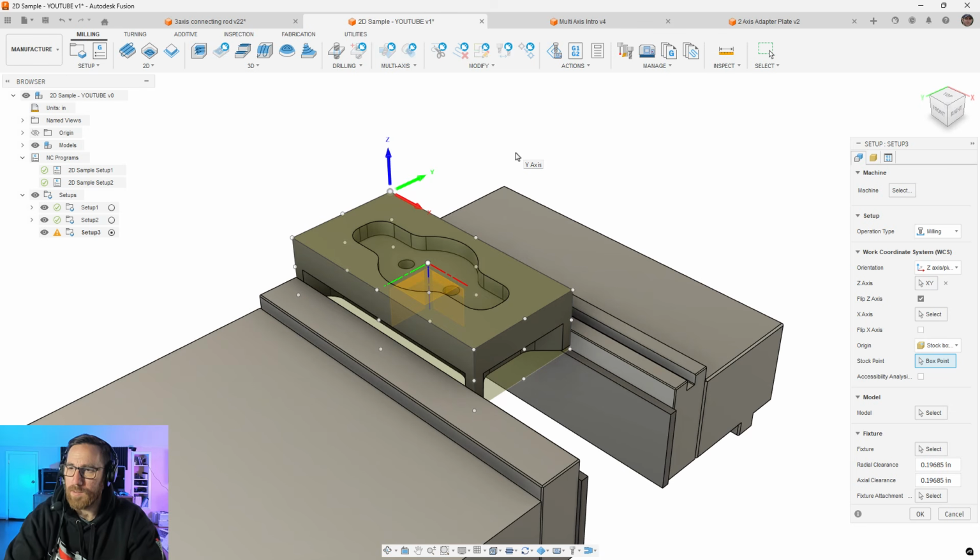If you're trying to do this on your own at home, many of these desktop machines will have automated coordinate system finding, depending on which machine you have. If you have to do it manually, then basically what you need to do is set the coordinate system in your machine at 0 at that corner. There's going to be a coordinate system for the machine, and then there's going to be a coordinate system for work. We'll talk about that in just a second.